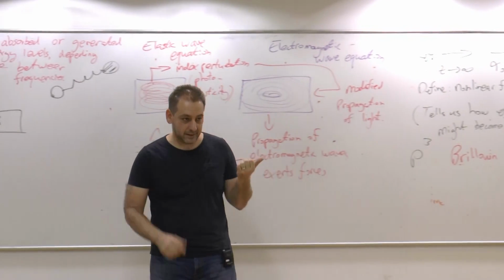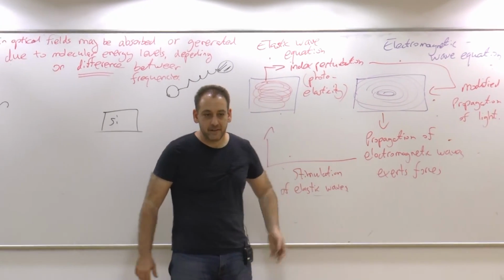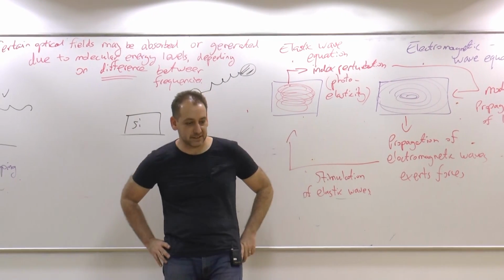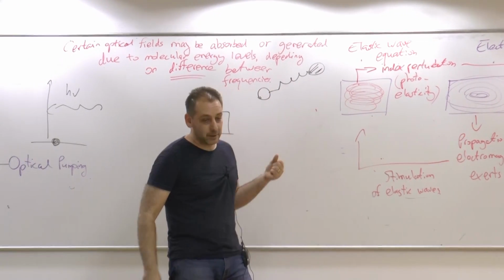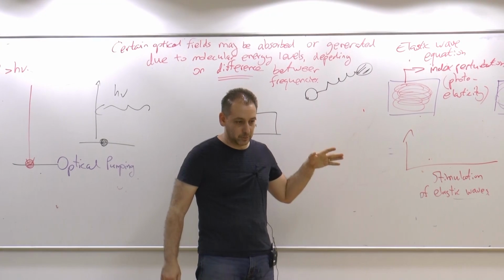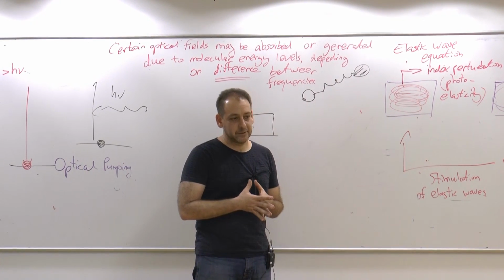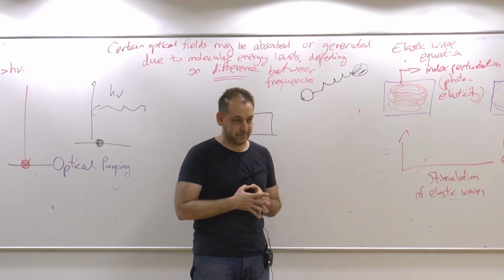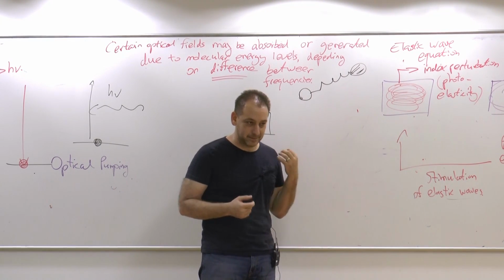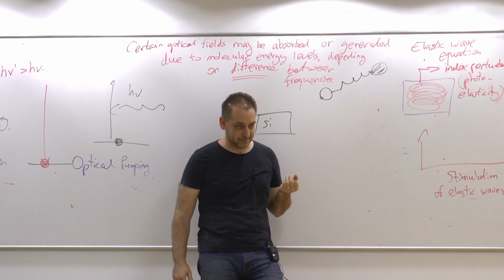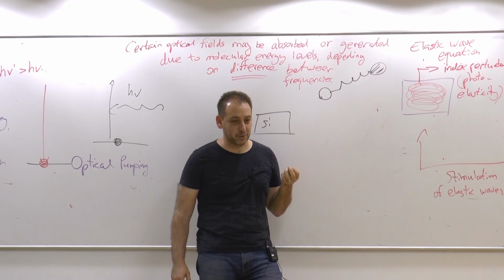Just to give one bit of information, there is a paper that is about to come out in a few weeks in Nature Photonics that is describing a Brillouin laser, not in silicon proper, in silicon nitride. The line width of these lasers is 0.7 hertz. Think just how incredible this number is. We're talking about a frequency of 200 terahertz plus and minus 0.7.